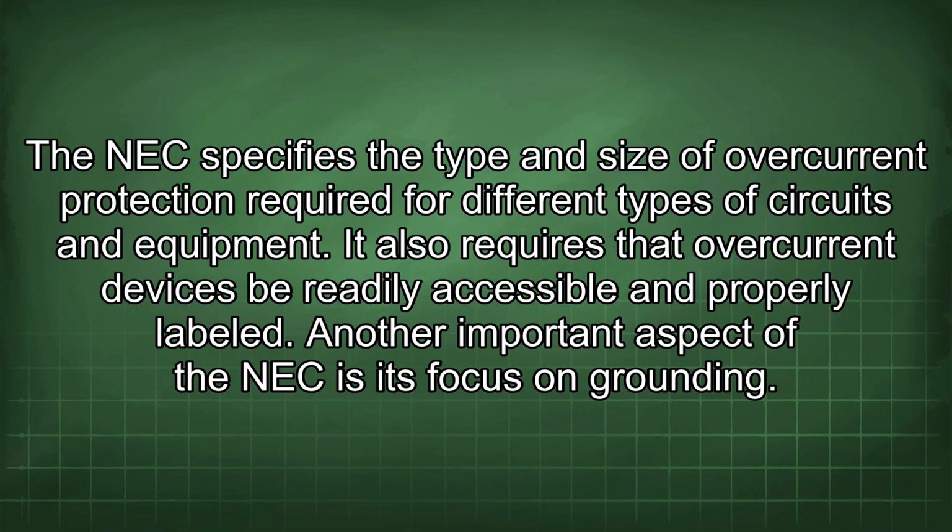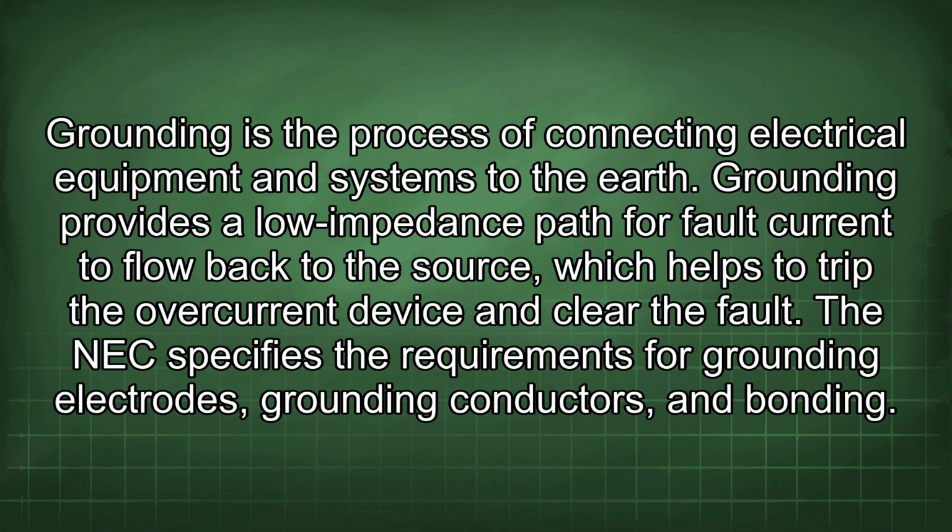Another important aspect of the NEC is its focus on grounding. Grounding is the process of connecting electrical equipment and systems to the earth. Grounding provides a low impedance path for fault current to flow back to the source, which helps to trip the overcurrent device and clear the fault.